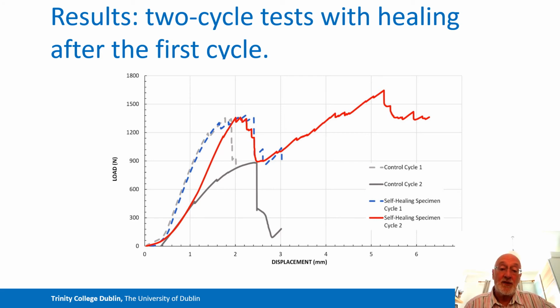We bend it. We're plotting load against displacement in a test to induce ovalization, like would happen in bending. And so we go up. We get a point where the fracture starts, and we get a drop. Okay, that's the grey dashes. If at that point we then unload and load up again, then of course the next one, the solid grey line, is not as good. It comes back to the place where we left off. It goes on a little bit further, and then we get more fracture events as more of those cell walls fail, and the thing goes to pieces, right?